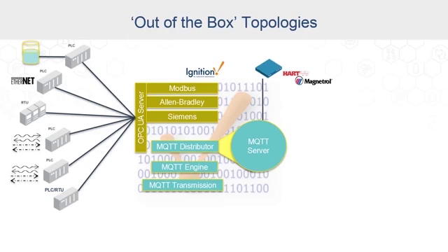So if we start putting together a migration strategy, let's look at that tank level transmitter in the upper left-hand corner. Even though that is a HART smart transmitter, and it's got hundreds of tags of information and metrics and asset information, when it was last calibrated, and multi-process variables, typically out of those hundreds, we take one process variable, i.e. the 4 to 20 milliamp loop, and we tie it into a PLC, and then we poll the PLC to get that single value.